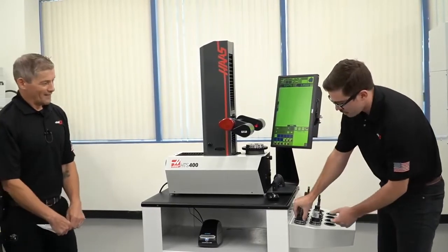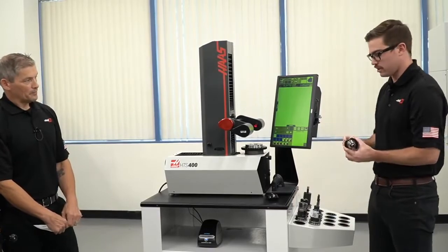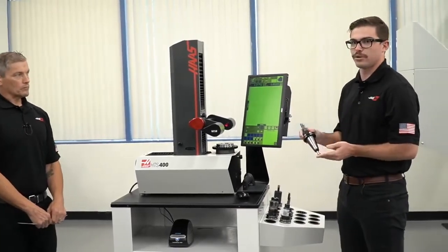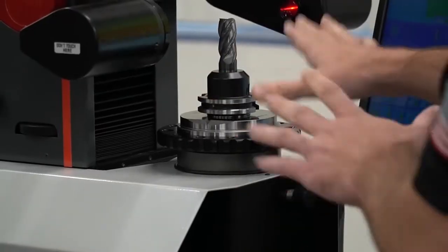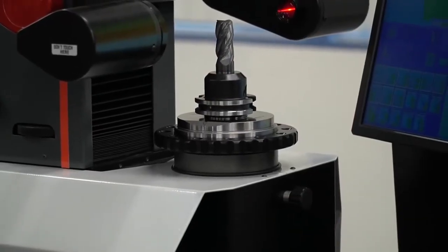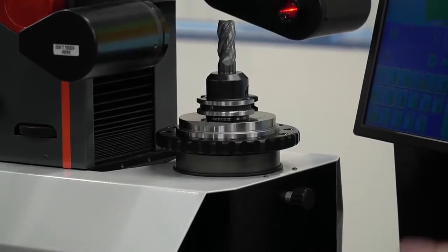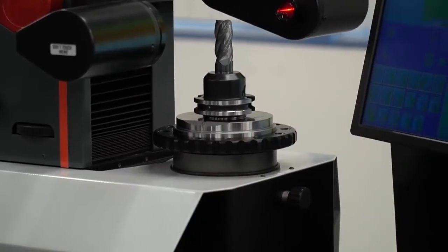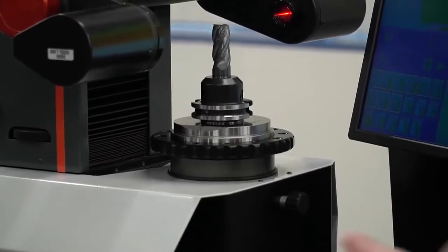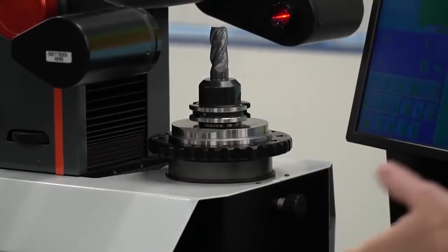Yeah, so you start by grabbing whatever tool you need. In this case, this is going to be a 3/4 inch Cat 40 end mill with 4 flutes. I just set it and drop it down right here into my tool sleeve. So it just sits in there with gravity, right? Yep, and then when you calibrate it, it makes sure that you've cleaned everything. Exactly, no dust or stuff. Sometimes you have dust, you just clean off the top, and that's really easy.